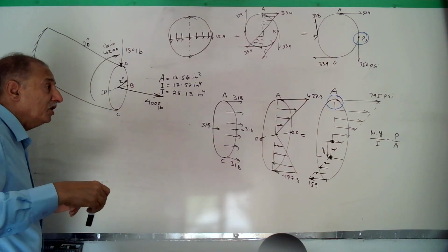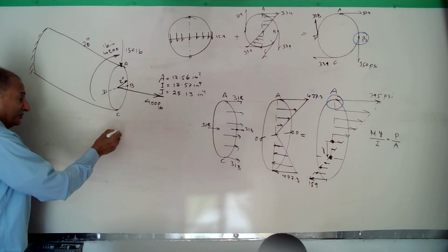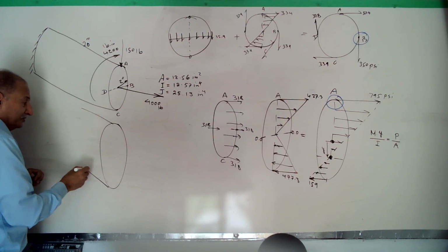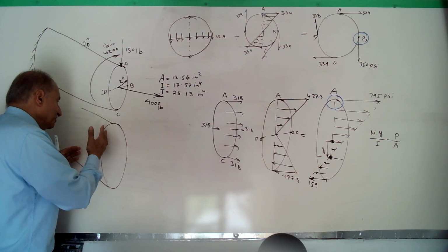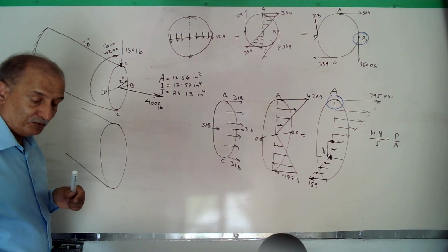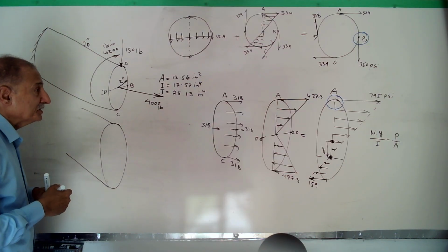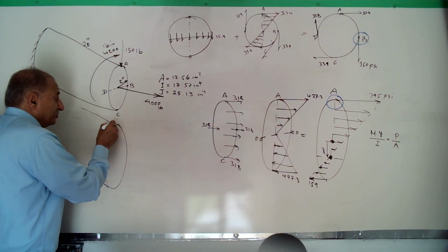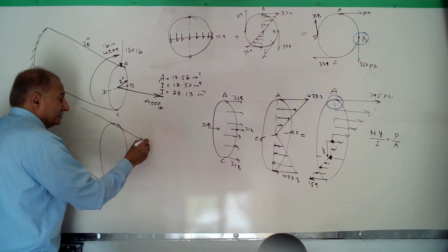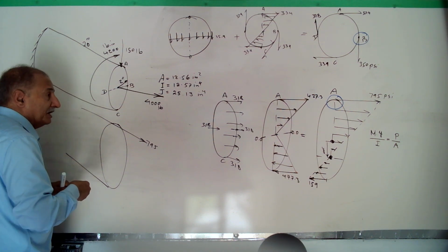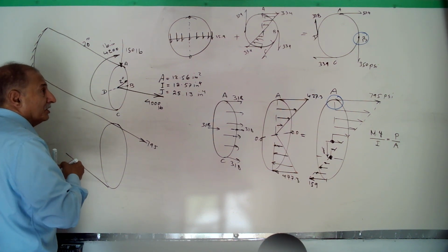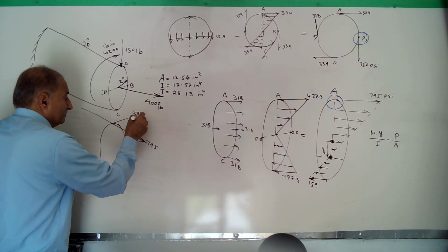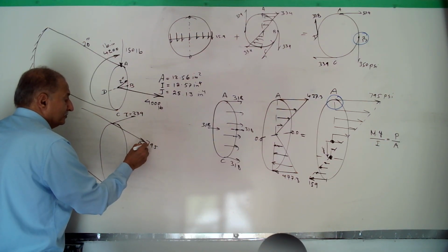Okay, let's show all of them together. All stresses. This is the shaft, at one of the cross sections close to the fixed end, because the maximum tensile stress happens at the fixed end. Here you have a normal 795 and you have a shear 334. Tau, sigma.